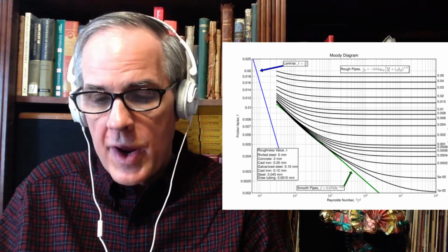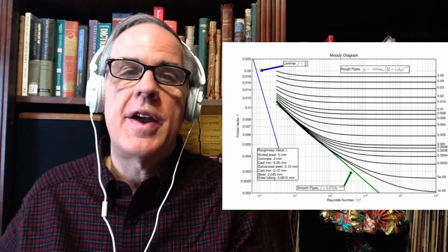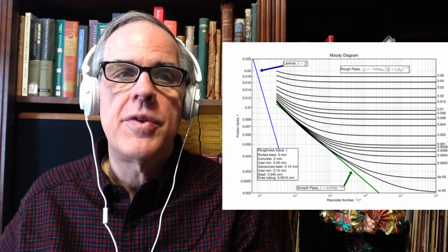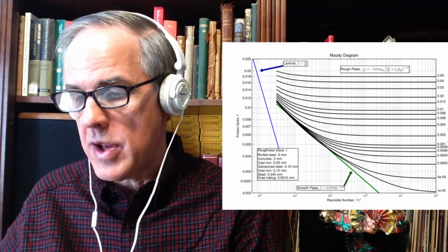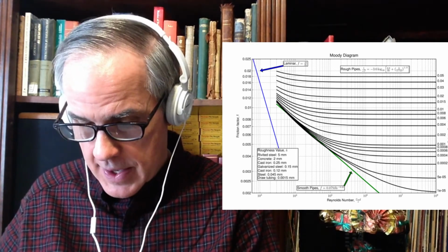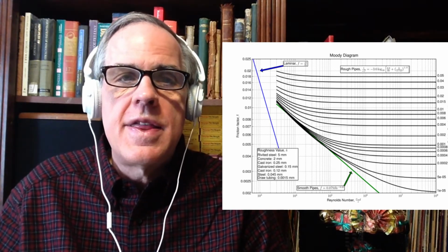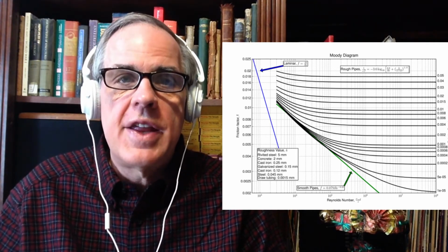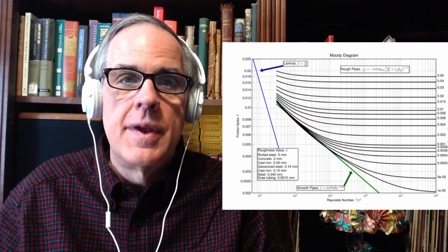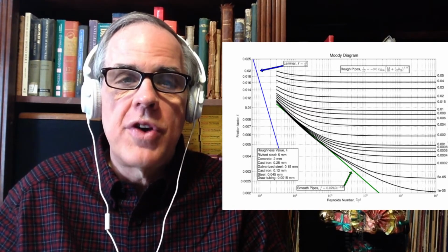Over on the right is a thing called the friction factor. We take that friction factor and use it to determine the head difference, or the head loss, in a stretch of pipe. So obviously from the Moody chart, you need to know,